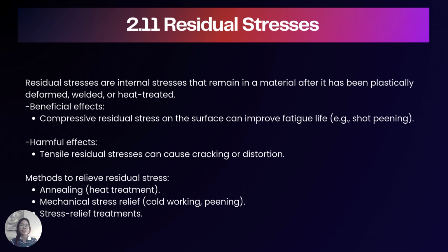Residual stresses are internal stresses that remain inside a material even after the external forces have been removed. They often result from manufacturing processes such as plastic deformation, machining, welding, or heat treatment. These stresses are locked in at the microscopic or macroscopic level.